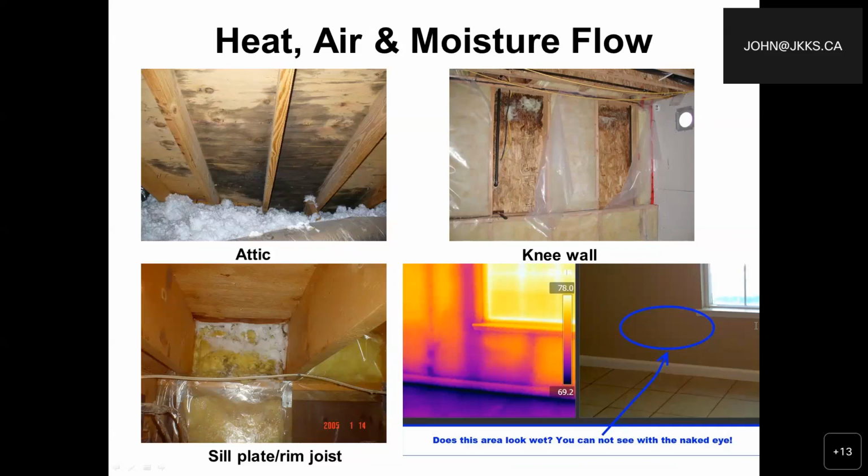It's a silent killer. I know we did some radon testing here maybe about a year or two ago, and one house had a high becquerel reading, like over 1,000, and another house had less than 200, and the other house had about 800. It varies from one lot to another lot. That's right, and that's the challenge with radon gas.